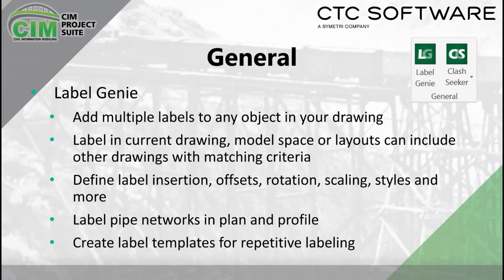And we can label things in model space. We can label them specific to a layout. We can even include other drawings if they have matching criteria. So we can define our label insertions. Different from your annotation tab, we can give it an XY where it's not completely dependent on your style. We can give it offsets, rotation, scaling, styles, and more.